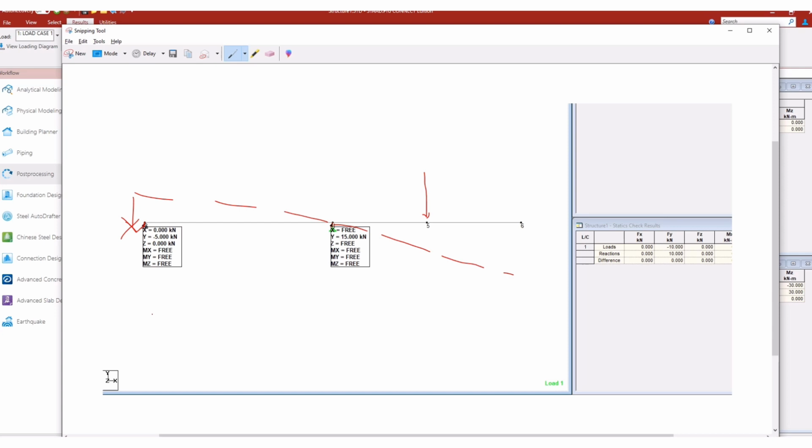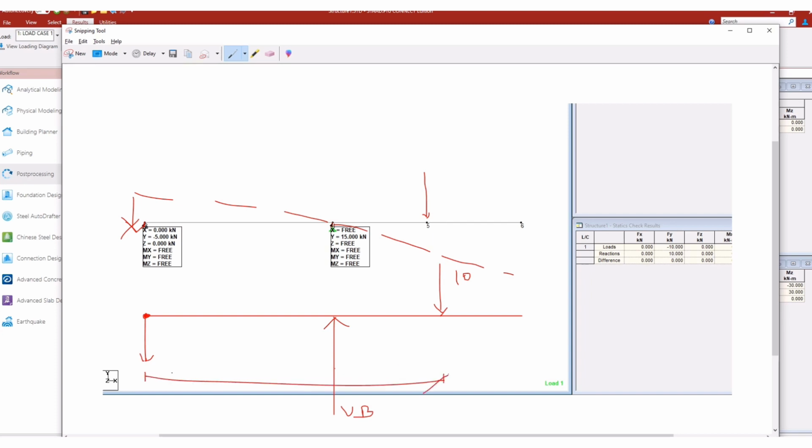So this will be held in position, so the reaction will be downward. Since this is minus direction, and this is also minus direction, this is 10 kilonewton and this is some value. At this location the reaction should be more than this value. If I take moment about this point, 10 into this distance is the lever arm. Since the lever arm is more here, but for this reaction the lever arm is less, the force would be more, and only then will the moment be equal. So moment is 10 into this distance, say for example 5 meter, that means 50 moment.